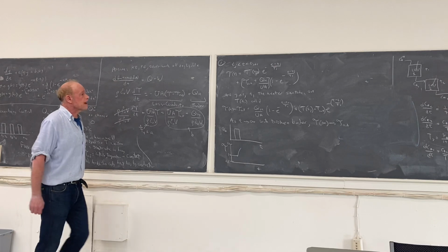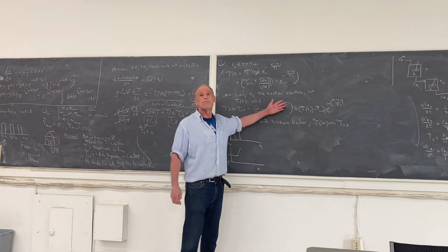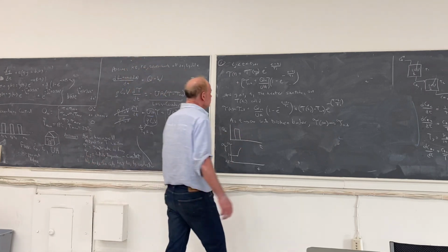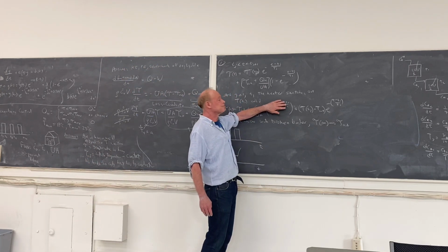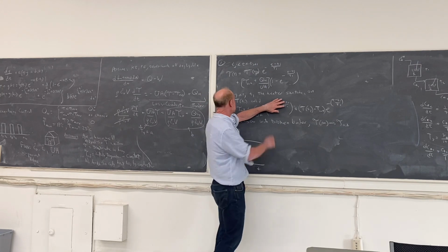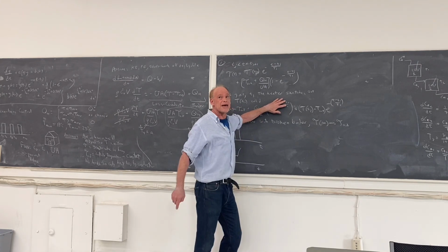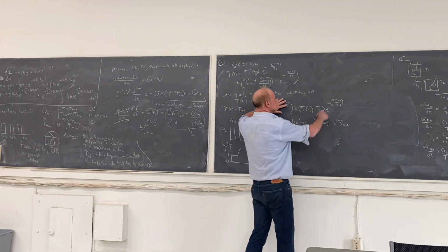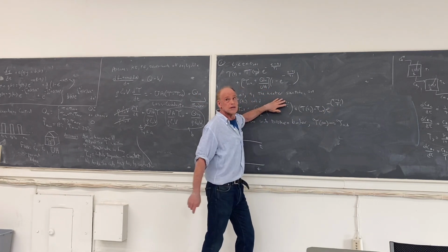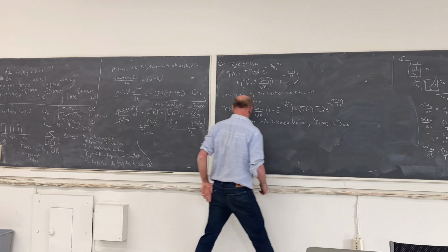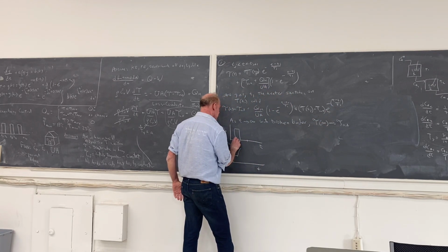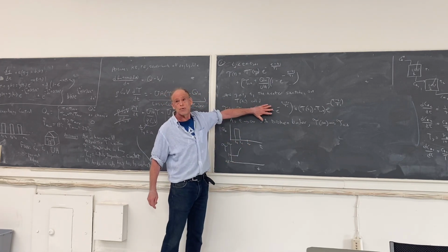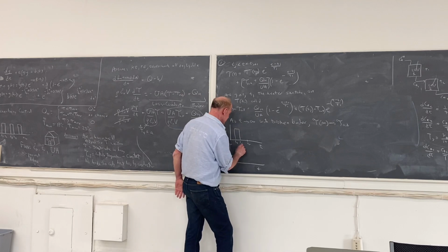Now what happens? Now all of a sudden QH becomes 0, but the equation stays the same because I did it for any QH. Now all of a sudden QH is 0, and here's my solution. And now what happens is that the amount that the temperature exceeds T out starts to decrease exponentially with a time constant T1. So during this next phase, T1, T2, T3, it's the same solution but with QH equal to 0, and now I have an exponential decay.